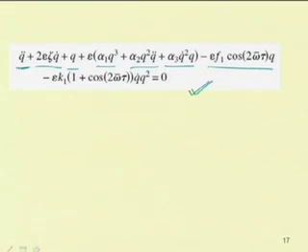So, in this case, for this cantilever beam subjected to a magnetic field, one can have this type of governing equation. You can observe that the coefficient of Q is a periodic term. So, this is a parametrically excited system along with cubic, geometric and inertia nonlinear terms. Similarly, you can have another nonlinear term also. So, this Q dot Q square is a nonlinear term. This Q has a coefficient cos 2 omega bar t, that is a periodic term. So, you have a linear parametric term and a nonlinear parametric term also in this equation.